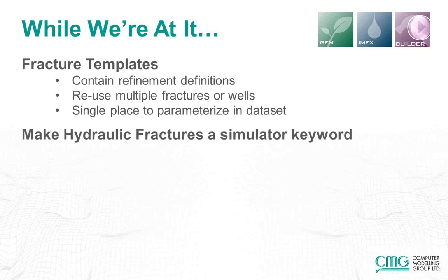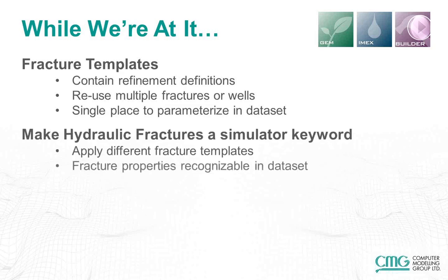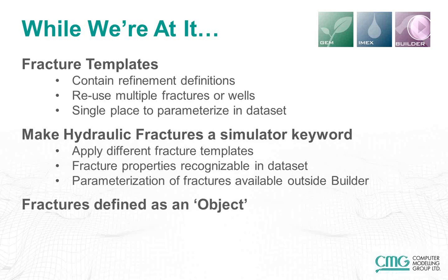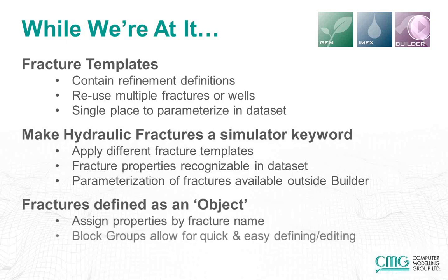The hydraulic fractures are also now a simulator keyword, so you'll see specific definitions now listed in the data sets. So instead of seeing permeability changes in refinement, you'll now see more recognizable things such as half-length, height, as well as the fracture properties such as width and permeability. The fractures will also now be defined as an object, which allows us to more easily adjust some of the other properties associated with the hydraulic fractures.